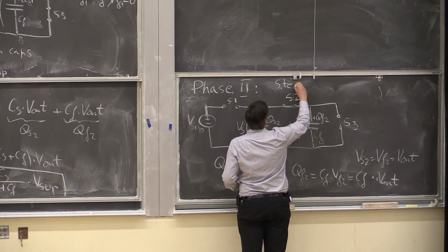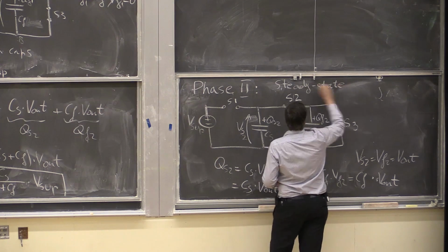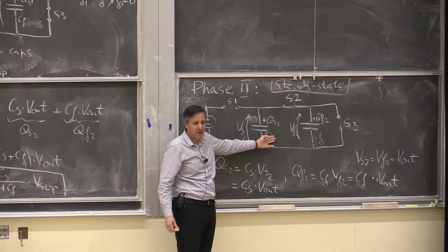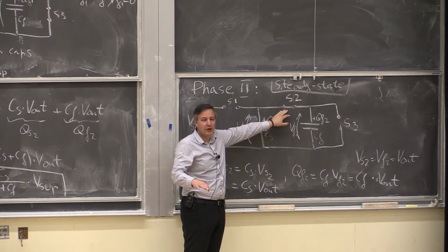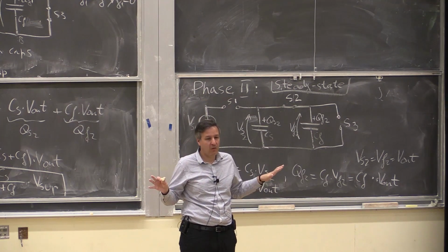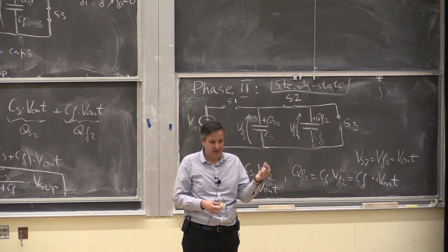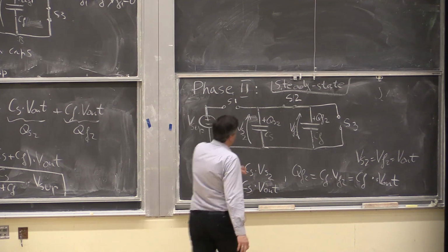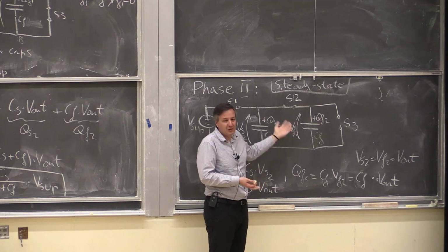The key word is steady state. Okay? So when I draw a circuit like this, and now this switch S2 turns on, I'm going to turn it on, and I'm going to walk away and wait for everything to settle in that circuit. You remember last lecture we said if the switch is not ideal, there's a little time before the capacitor gets charged through that switch, right? And here we're using ideal switches, so you don't have to wait anything.